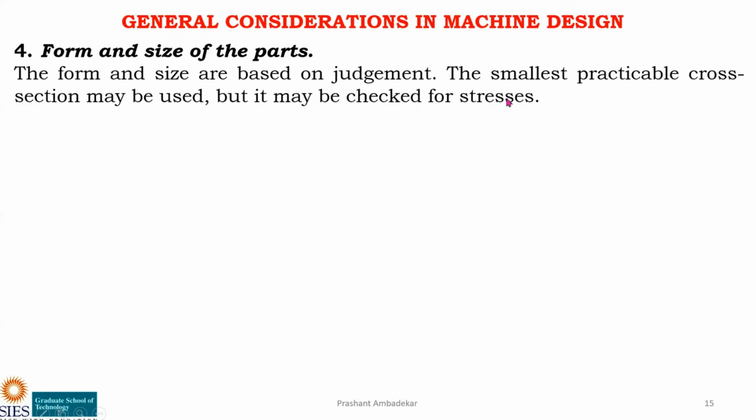So this point will be more clear when we will solve a few numericals. Maybe in the next lecture we will solve numericals. That time you can remind me of this point. Even though by calculation you are getting 10 mm, still 8 mm may also serve the purpose. So it should be based on judgment. You should be able to take the decision whether to use a 10 mm bolt or an 8 mm bolt.